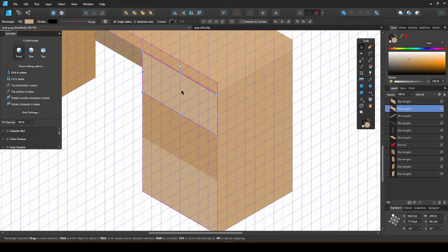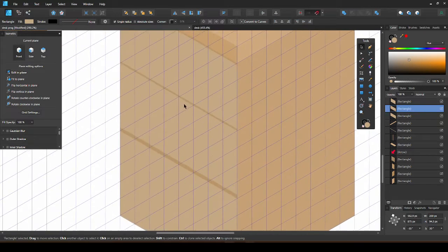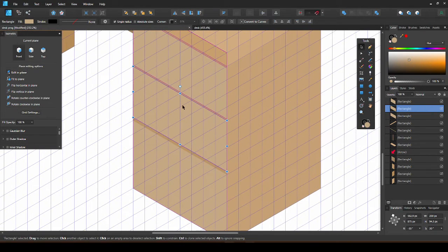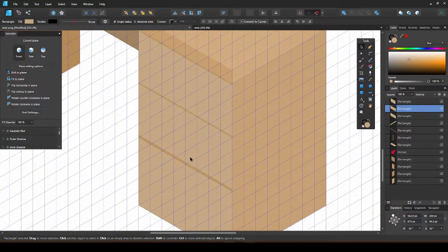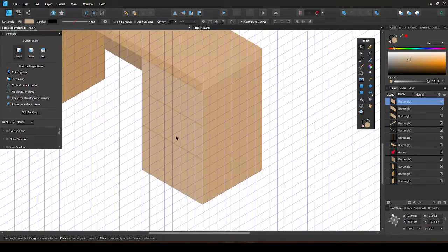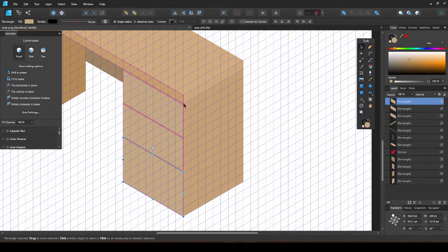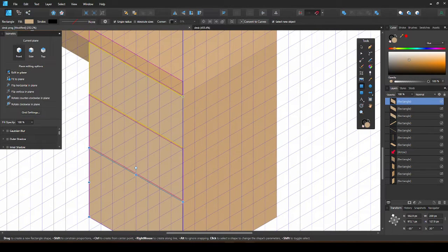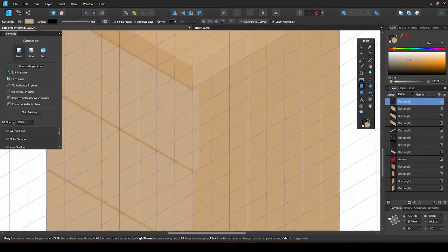And then copy it. And then adjust the bottom one as well. And snapping will allow us to make sure that those gaps are both the same sizes. Then I want the drawers to come around the side a bit, so making sure that you're in the front plane, draw another rectangle right here. Make sure it's the same size as the drawer.